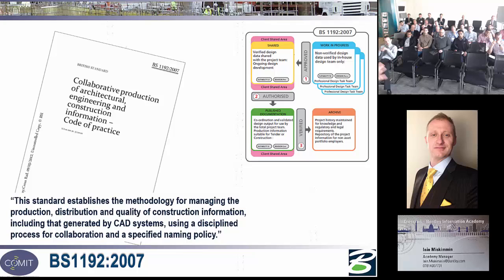So for those who have used it before, this is all old hat, but these four boxes are the key processes or the key stages of pushing information. So right at the very beginning, work in progress. That's the only place your information is ever amended. That's where all the drawing is done. That's where all the modelling is done. That's where all your documentation is written, whatever it might be. That's where it's always amended.